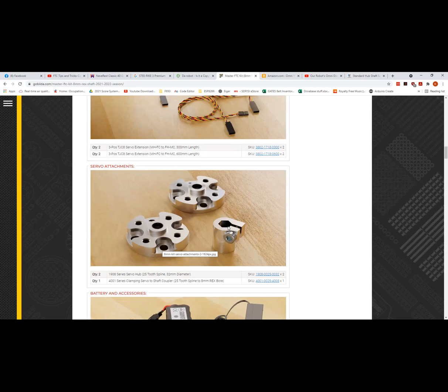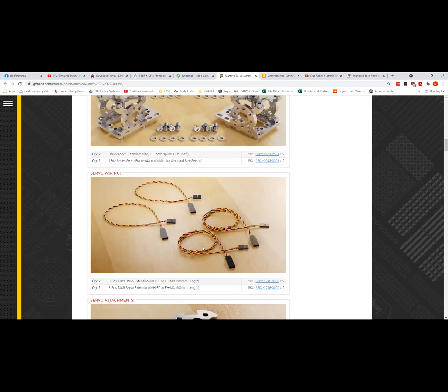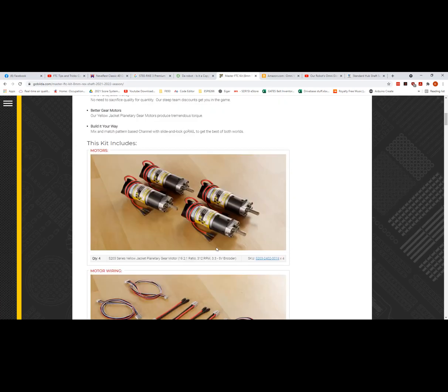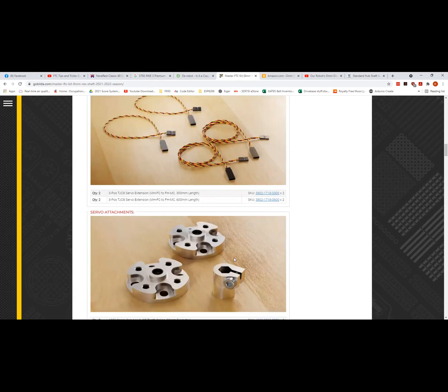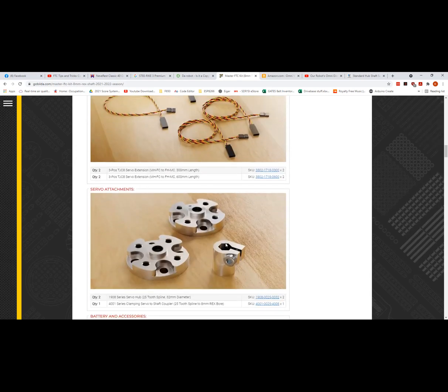These are 8mm bore. Oh, okay. If you need, you can buy a thing called a broach that'll allow you to drill a hole and make the hex shape in it. You'll need to figure out what size it is.